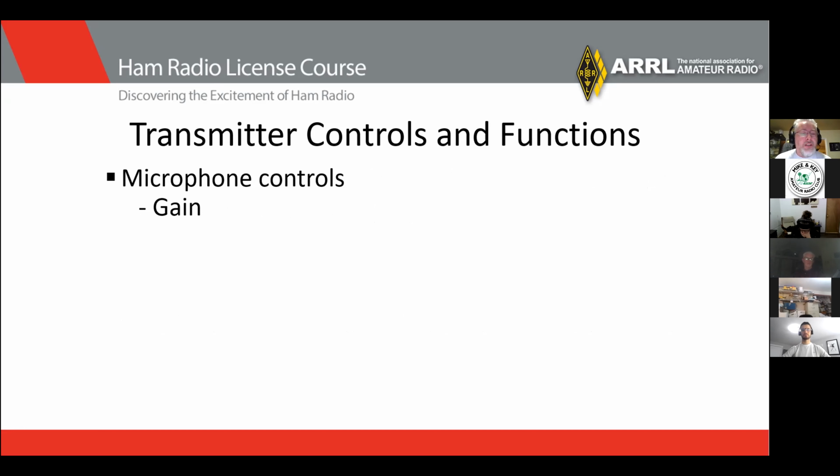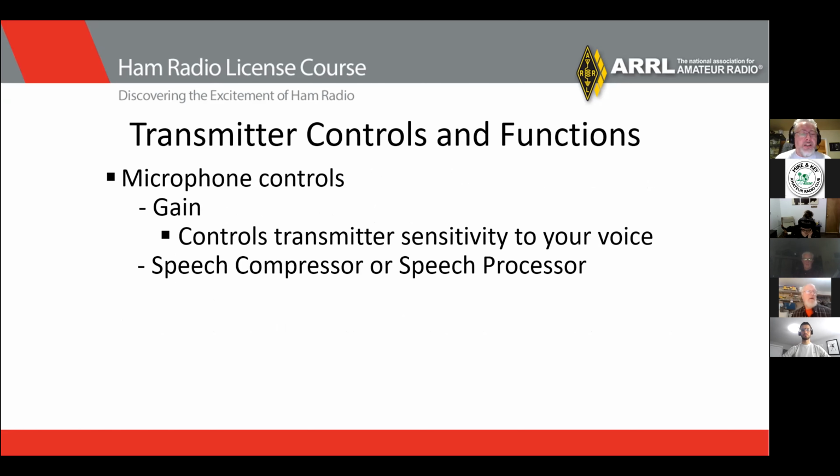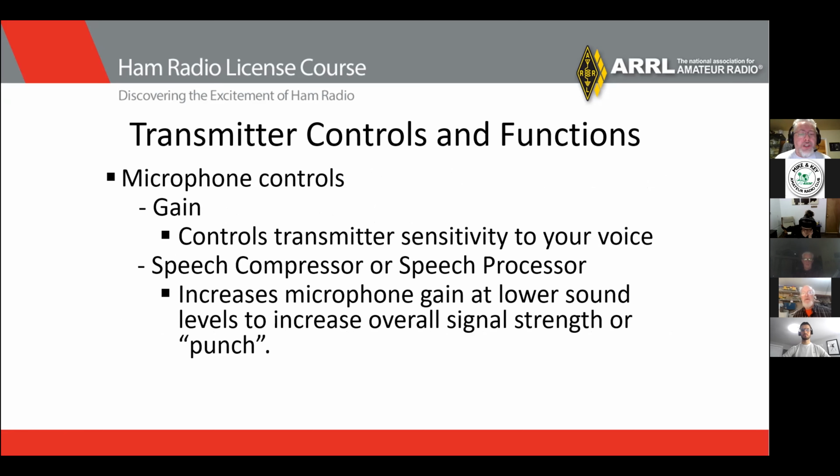Microphone controls have the gain, which controls the transmitter sensitivity to your voice, a speech compressor or a speech processor, which increases the microphone gain at lower sound levels to increase the overall signal strength or the punch.